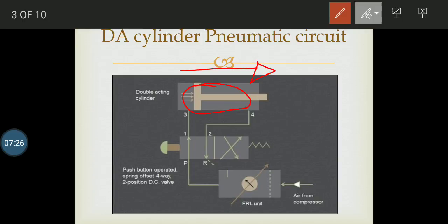and once the complete filling of the cylinder gets completed, it is now very important to change the direction of the DCV. So I am releasing this knob or the button. So once the button has been released, the direction control valve changes its direction from section 1 to section 2. So section 2 gets activated, and section 2 will look like this. Okay, it is having like this.